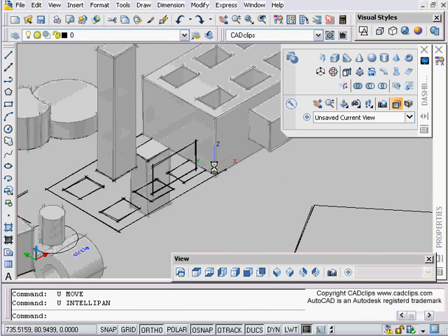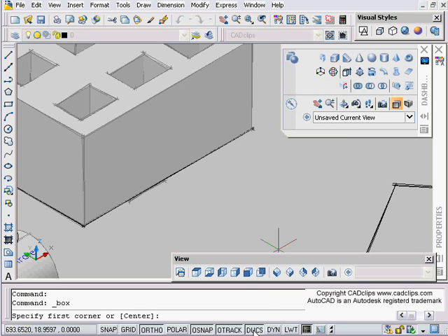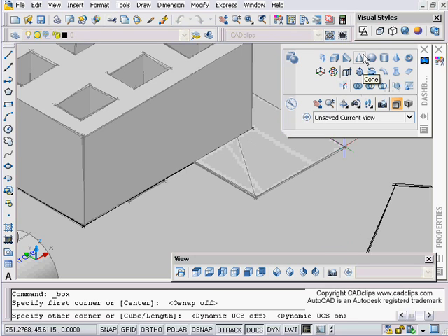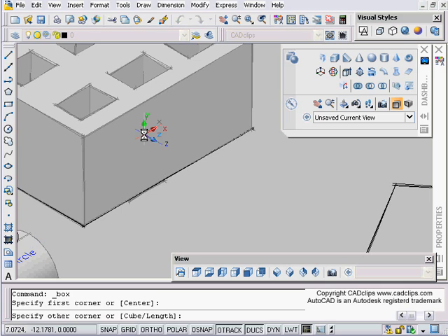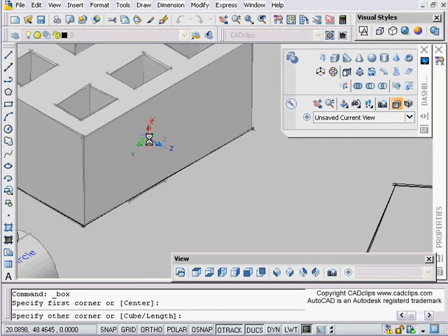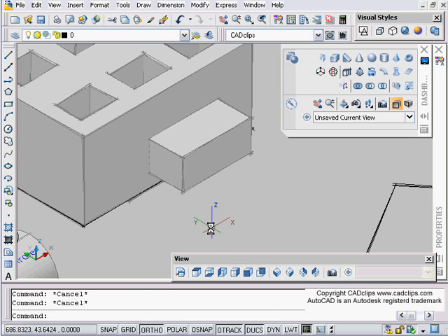because I did a push-pull off of that surface, as opposed to, rather than drawing a rectangle and push-pulling it, go right in here, use the box command using my dynamic UCS, turning my ortho off and hovering over there. Oh, sorry, try this again. Box, hover over here, click. And then, oh, I'm still getting the wrong surface. Here, there we go. Click, and then pull.